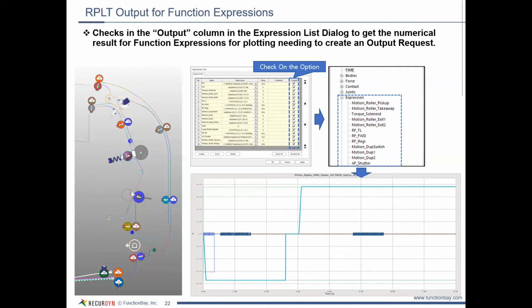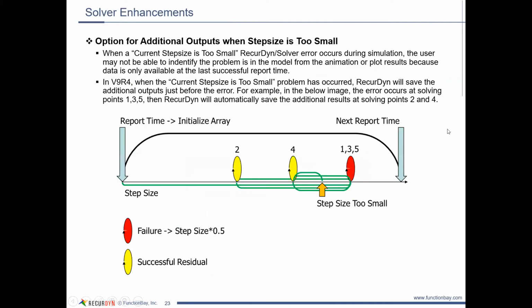So I'll make a copy of it and then take that copy and subdivide it into a bunch of independent expressions. Then I want to look at the plot data for all of them so I can get a feel for which piece of it has the unexpected values. With that approach and being able to use this output option, it's very quick to get all the feedback information you need.